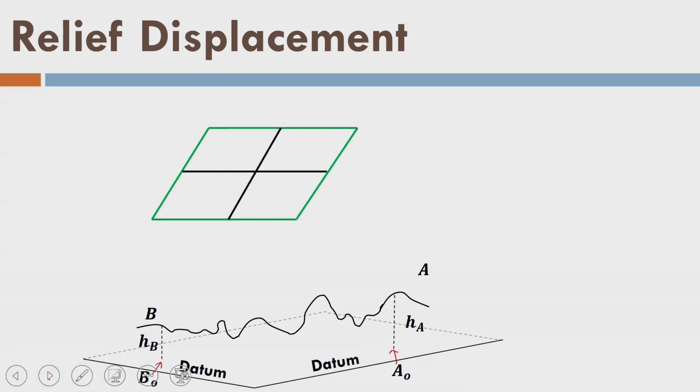Okay. So, let us say there is an image and there is an exposure station, and this is the optical axis which is piercing the datum here at K0, and I have the principal point k here. If I extend the optical axis, or the nadir line, so that the principal point touches the ground surface, then in the gravity direction it is this point here, fine. Okay. So, the height of the point K with respect to datum is HK.